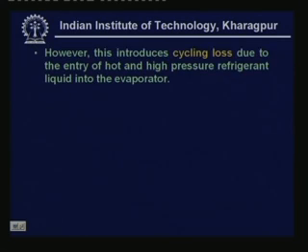Whenever there is a pressure equalization, it introduces what is known as the cycling loss. Okay, and what is cycling loss? Cycling loss is nothing but the entry of hot and high pressure refrigerant liquid into the evaporator.